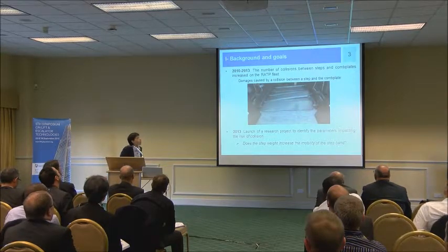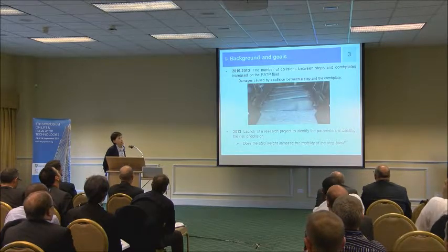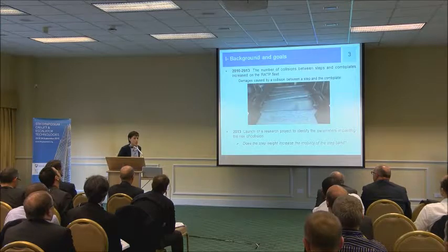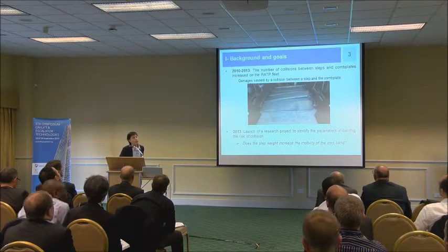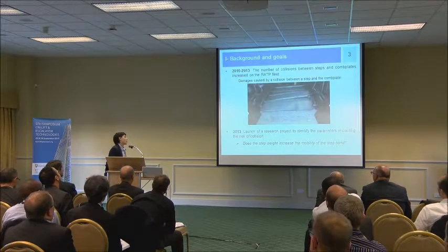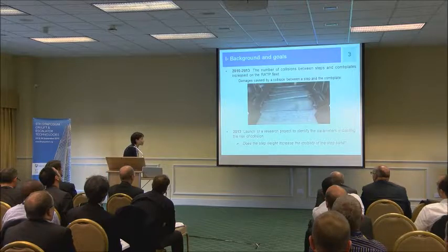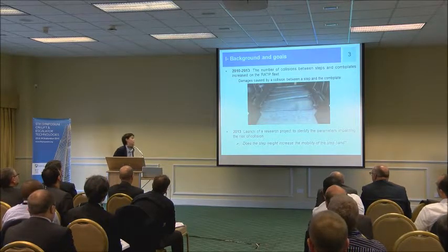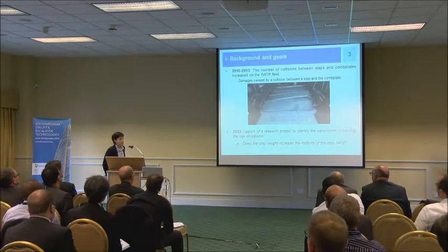So the idea was to assess the impact of the step weight on the dynamic behavior of a step band. For this purpose, we created a multi-body dynamic model. And we realized that we were able to study many more parameters than just the step weight, and to use the conclusions to optimize our maintenance policies and design methods.